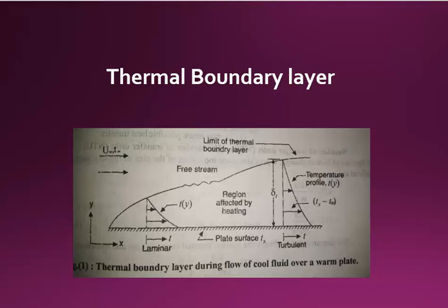These parameters provide a useful definition of the characteristic measurable thickness of the thermal boundary layer, and also included in this boundary layer description are some parameters useful in describing the shape of the thermal boundary layer. If we discuss the 99% thermal boundary thickness, the thermal boundary thickness, that is del T, is the distance across a boundary layer from the wall to the point where the flow temperature has essentially reached the free stream temperature T naught. This distance is defined normal to the wall in the y direction.